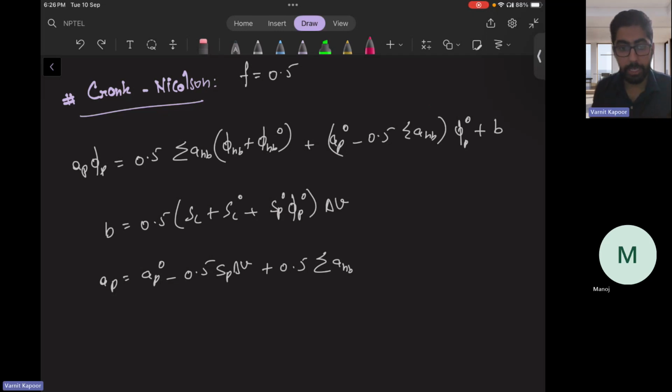So there is a truncation error. Different kinds of errors can be there. So we have to quantify truncation errors, which can be because of the profile assumptions. All right. So in steady diffusion cases, there is only a spatial truncation error. Whereas in unsteady diffusion, we have spatial as well as temporal truncation errors. Whatever that order of delta t or order of delta x we are dealing with, those are the truncation errors we are taking. Okay. Let me write the heading.